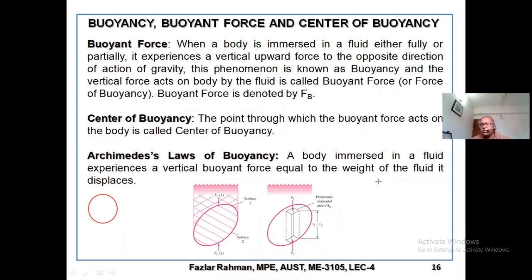So the weight of the fluid is also a force, right? Mass is in kg. So if you have volume, you can figure out the weight of the fluid equal to rho g V, right? Rho into volume, you get mass. I'm sorry, you get mass, then you multiply by g, you get the Newton. That is the weight. Weight is actually force, unit is Newton.